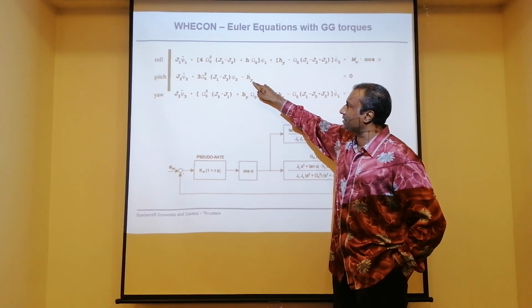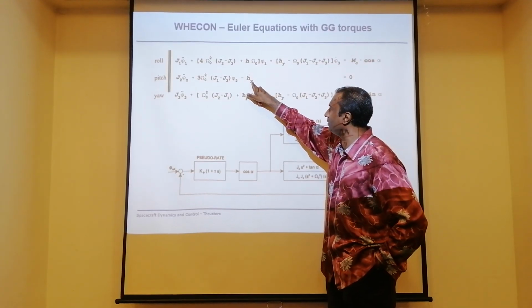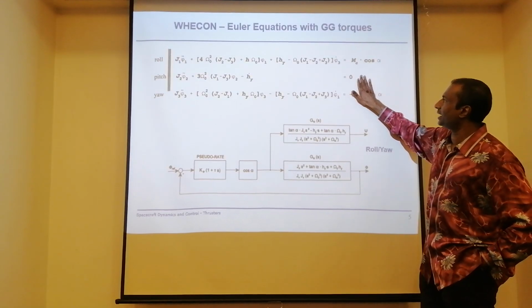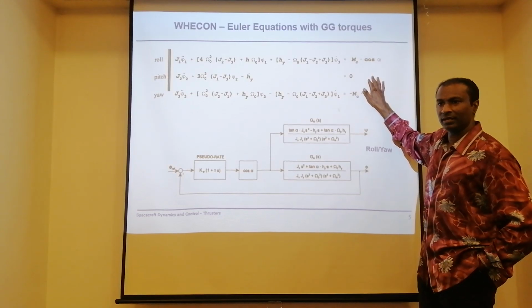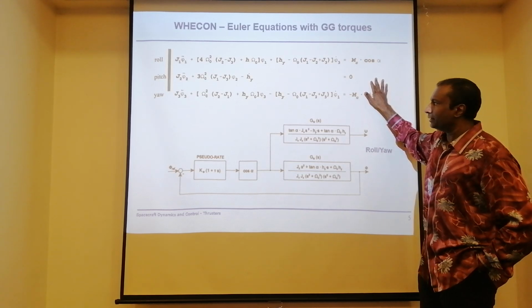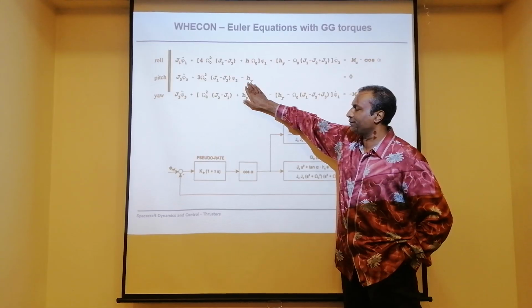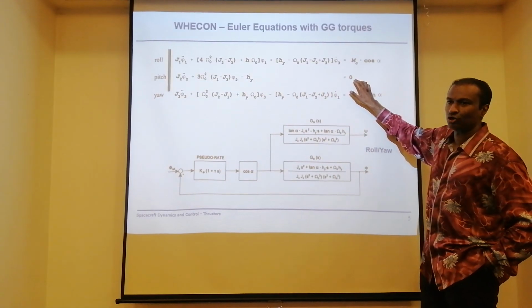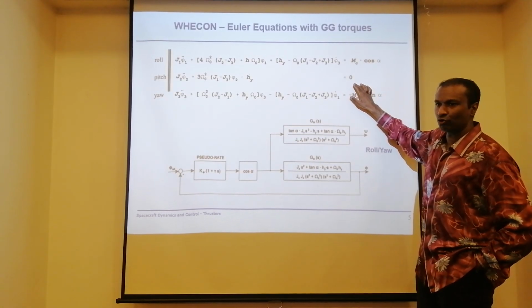That means if I increase the speed of that momentum wheel, I should be able to have a torque. Again, remember all those disturbances will be on your right side. So there is a disturbance here actually. I didn't write it, but you will have those exact disturbances. Okay. So let's say I move that pitch axis. Let's say I move this torque. Control torque here. Here will be plus H dot, and this is a torque. So this is an internal control torque.